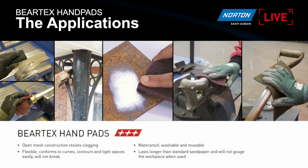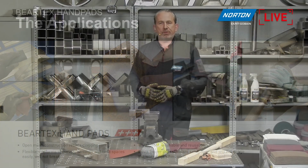They'll last much longer than the standard sandpaper, and the big benefit of these is that they're not going to damage or gouge your component or workpiece when you start using them. So they're not designed to change the size or the geometry of the component. They're there just to put a nice surface finish on, or blend or clean. Exactly. Okay, thank you very much for that, Robin.